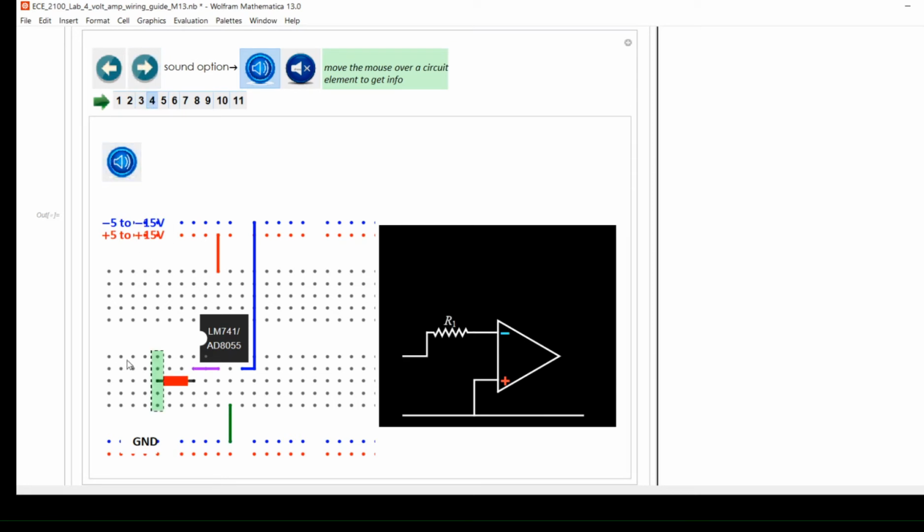Connect the 1 kΩ input resistance with wire to the inverting input pin 2. Put in feedback resistor 1 with wire connected to the op-amp output pin 6. Connect also a wire from the inverting input pin 2 to a location near the feedback resistor, but not to connect to it. Later, we will use a jumper wire to connect to the different feedback resistors. If you have a multi-position switch, connect the wire to the input position on the switch, while the feedback resistor should be connected to a switch position, such as position 1.